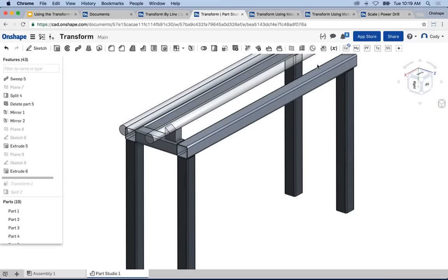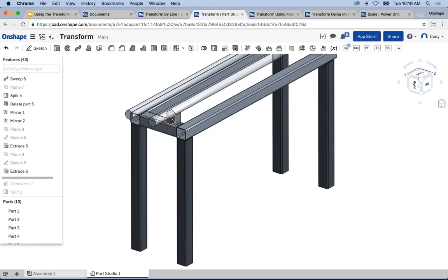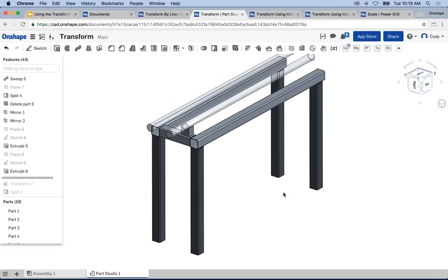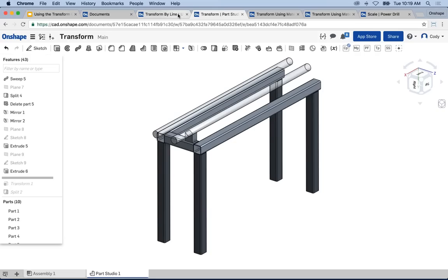And the main reason for that is when you go to create a bill of materials, your quantity counts will be correct and so on. So again, assembly motion, that's step number 1. If you need motion dynamic, you need to create assemblies. And also, if you have multiple instances of parts, like I have in this example, where I have maybe half a dozen V blocks, I would create an assembly and pattern those parts so that, again, the quantities are correct.